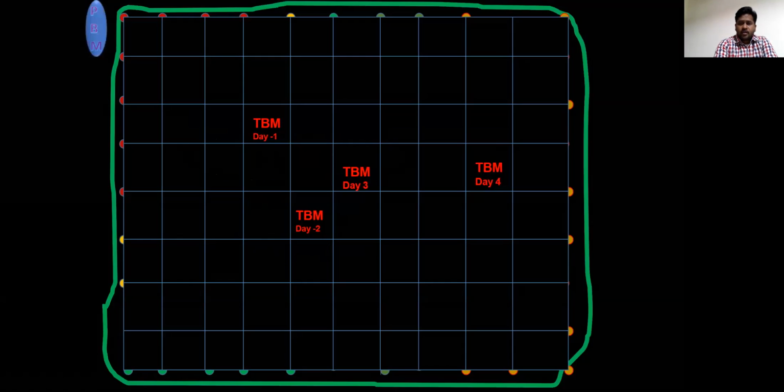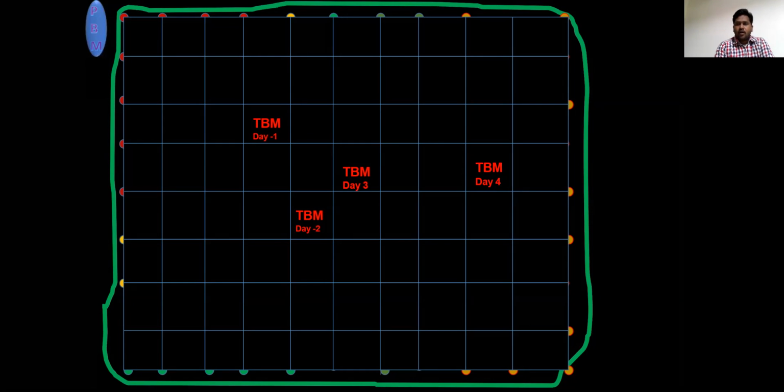These benchmarks have a very prominent role in conducting survey. Without benchmark, we can't conduct any survey, because only with reference can we do survey. Without any reference, we can't do survey. So if you want to prepare any map, the Survey of India has prepared all the maps with reference to the mean sea level, that is in Mumbai.